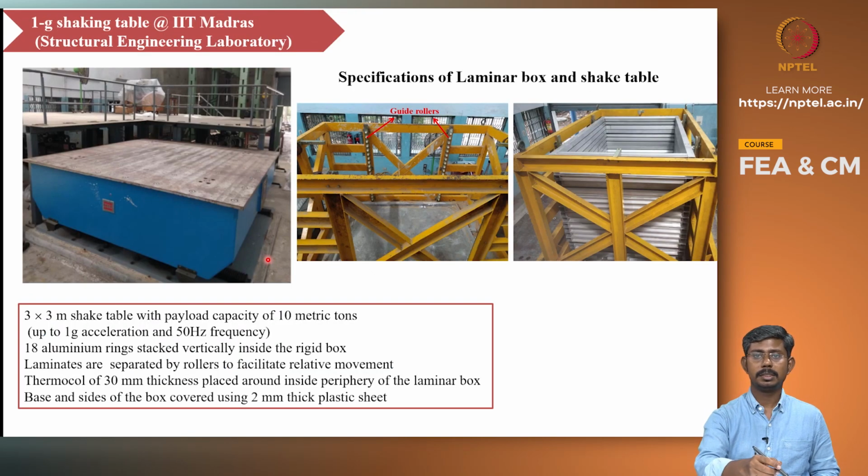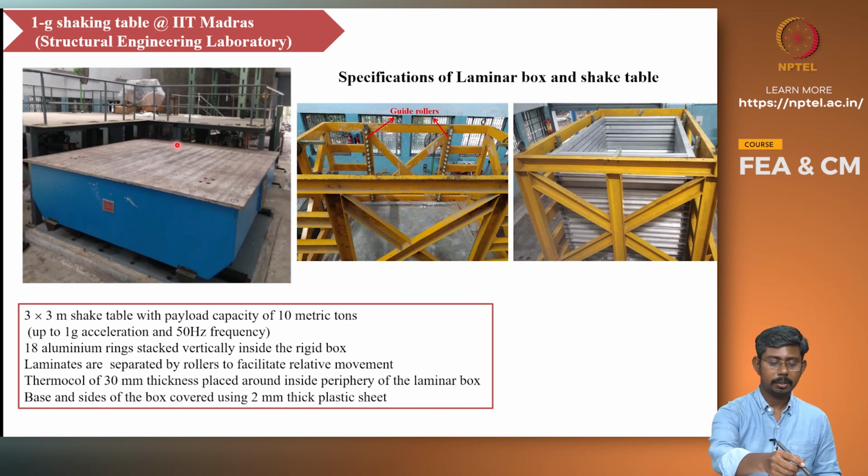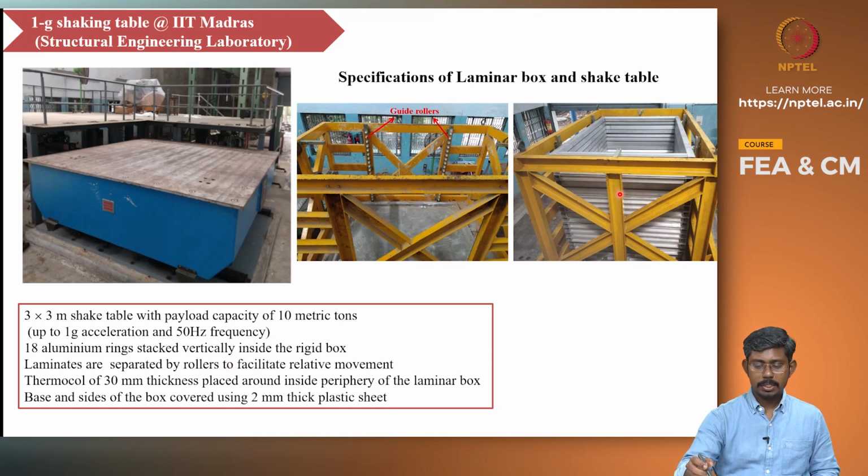Apart from the numerical simulations that were carried out using FLAC 2D and PM4Sand as a soil constitutive model, 1g shaking table tests were conducted to evaluate the performance of the granular columns. This is the shaking table facility available at the Structural Engineering Laboratory at IIT Madras. It is a 3 meter by 3 meter shaking table, which can handle up to 1 g acceleration and 50 hertz frequency, and the specifications of the rigid box are shown here.